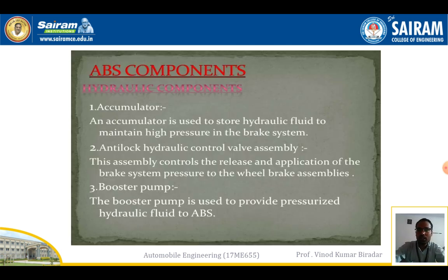So what are the components of an anti-lock braking system? If you want to study the working of this anti-lock braking system, you need to understand the parts of it. The first component is the accumulator. The main use of this is to store the hydraulic fluid to maintain high pressure in the braking system.